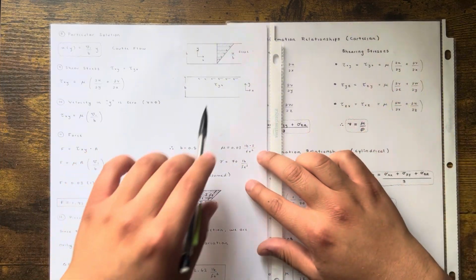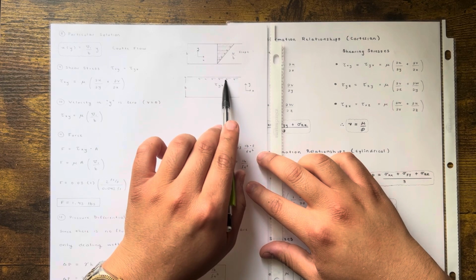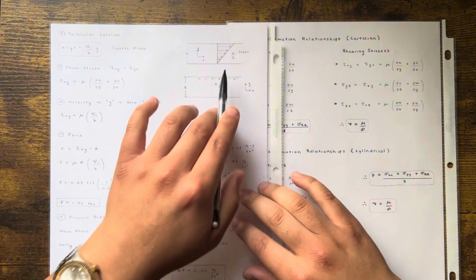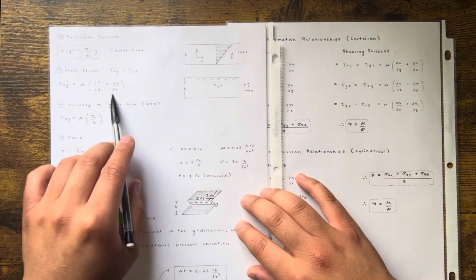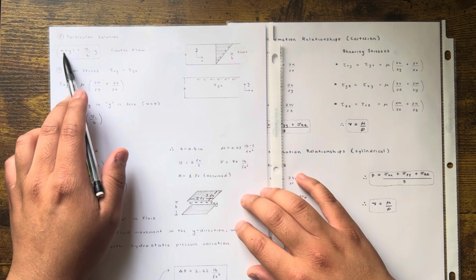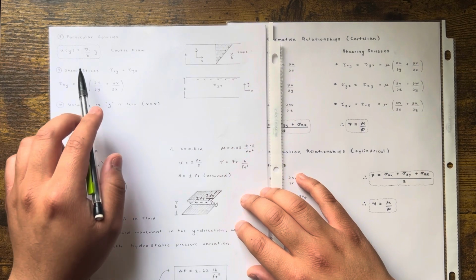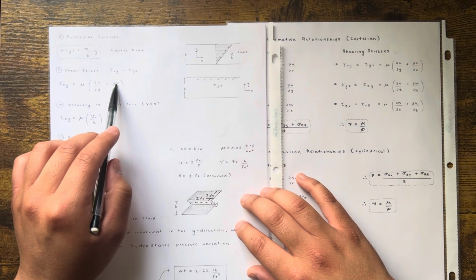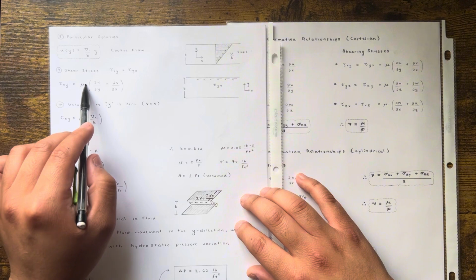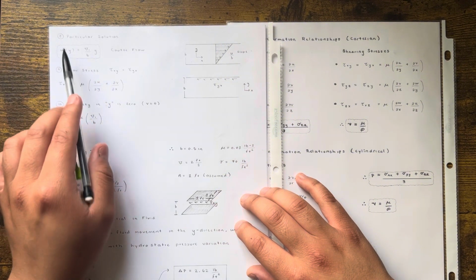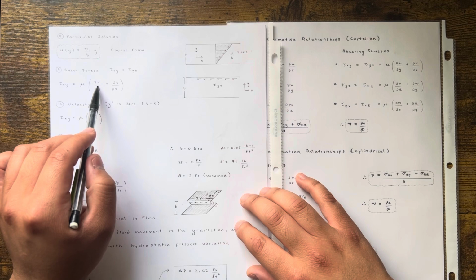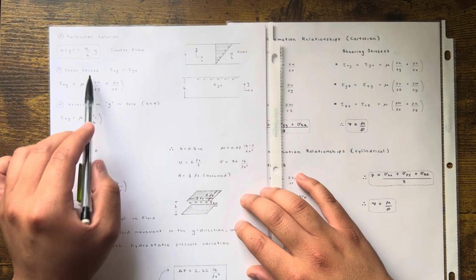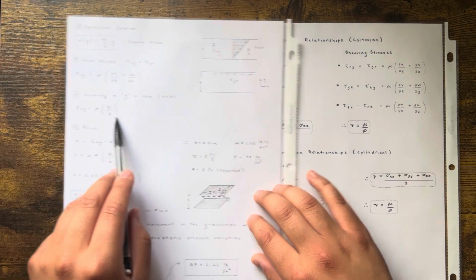Okay? And if you imagine the flow's moving this way, well, the wall's shearing in the opposite direction, right? It's like a sliding kind of thing, okay? So in this case, I use that equation. I know U, right? The flow in the X direction, the velocity profile. V is 0, so this term goes away. So I just have mu times the partial U partial Y. So I take the derivative of this function with respect to Y, and it's just U1 over B. So that's what I have here.